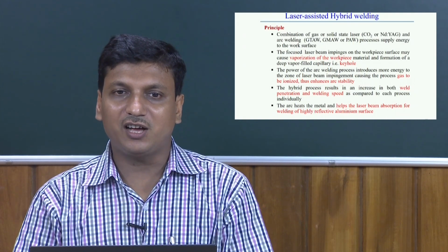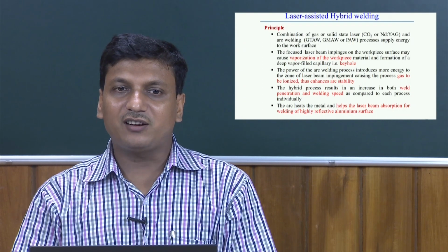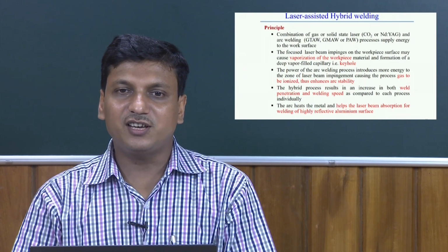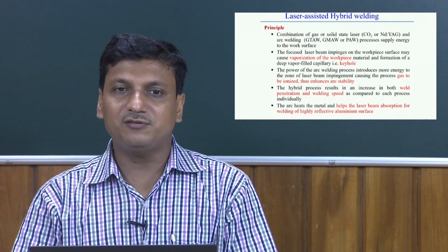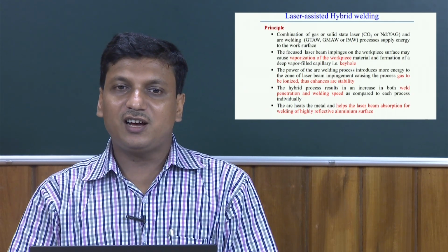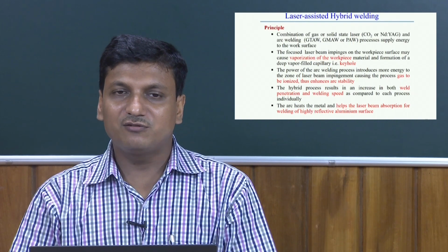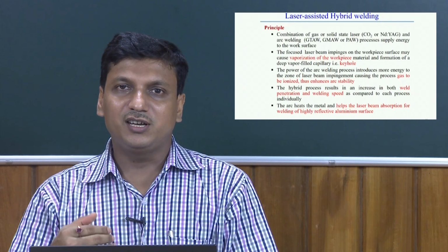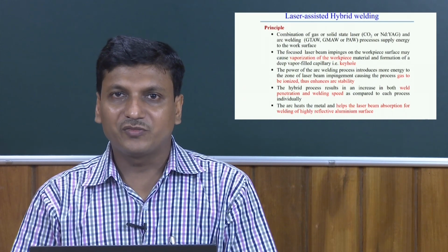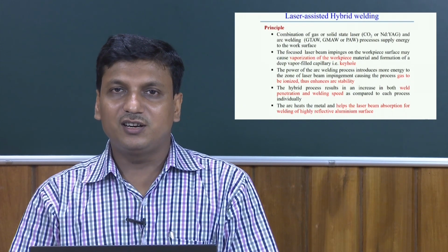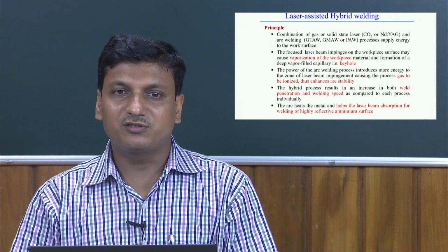But if you look at it the other way, the arc also helps by increasing the laser beam absorption, specifically when we try to weld a highly reflective material. For highly reflective materials like aluminum, the laser assisted hybrid welding process is actually beneficial.